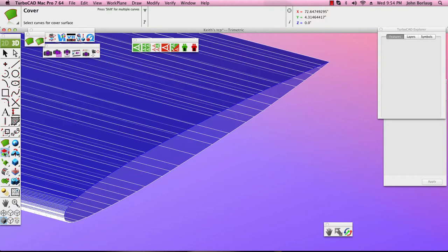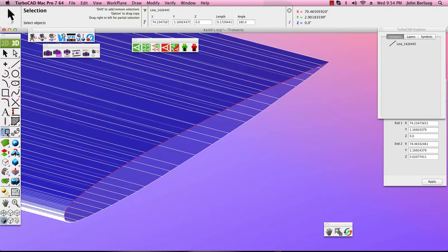So what I need to do then is explode. Okay. Edit, undo, curve, explode. That'll take too long for us to do that. So I will draw. I don't need to draw. I just need a point. I'm going to take that line and I'm going to set that up with a mirror using the XY plane. And Z0 and our XY. And there we have the line.